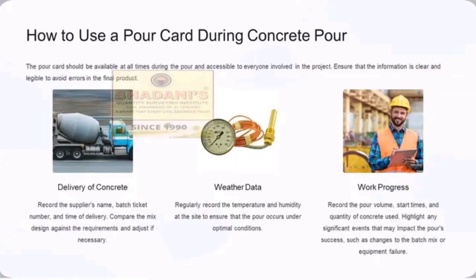Okay, and we will also ask ourselves how to use a pour card during concrete pour. How will you use a pour card during concrete pour? There is a statement up there that the pour card should be available at all times during the pour and accessible to everyone involved in the project. Ensure that the information is clear and legible to avoid errors in the final product. I had said that the pour card should be accessed by everybody to know the details of the pour, so that it can make the work efficient.